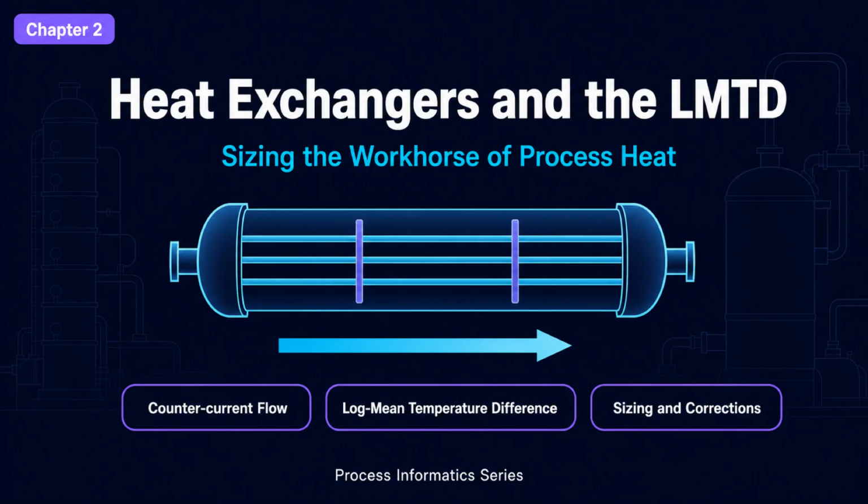Welcome to Chapter 2 of our Chemical Engineering Heat Transfer Series, Heat Exchangers and the LMTD. The subtitle is Sizing the Workhorse of Process Heat. Chapter 1 built the overall heat transfer coefficient U, the single number that collects film resistances, wall conduction, and fouling. This chapter spends it. Given two streams and a duty, how large an exchanger do you buy? The sizing equation is the same transport law in the same form, but the temperature difference now has to be made precise, because in a real exchanger it changes from end to end as both streams heat and cool.